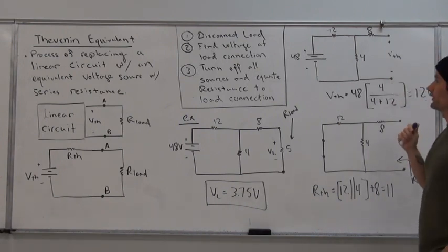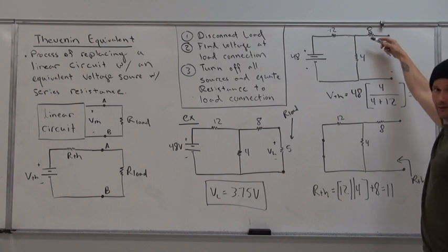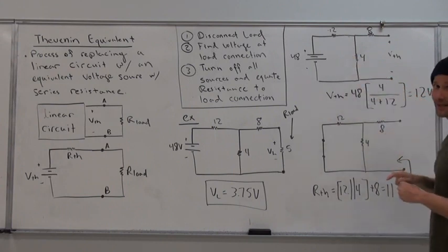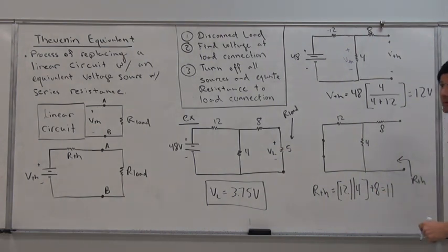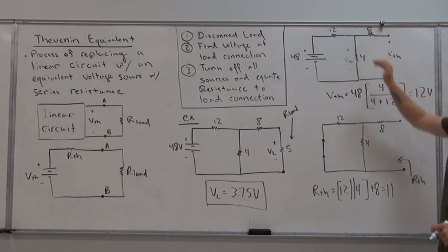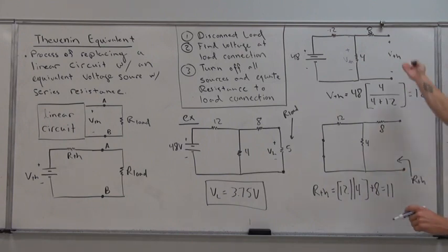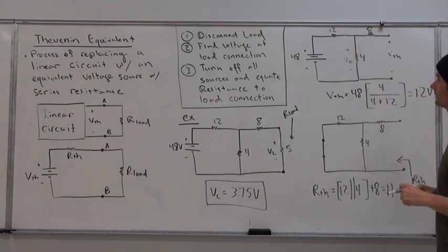And one thing that's a shame about not having everybody in the lab is that I love showing how this works, because it usually throws people off: how could that voltage exist right here across that 4 ohm resistor if we still have an 8 ohm resistor right here? But in fact, that 8 ohm resistor is acting more like a piece of wire, just a conductor, because there's nothing going through it. So it's simply allowing for a very simple series circuit.